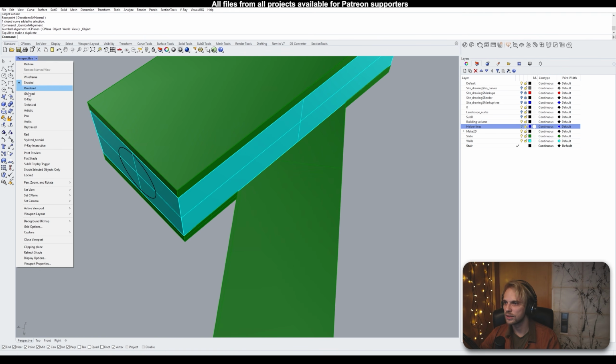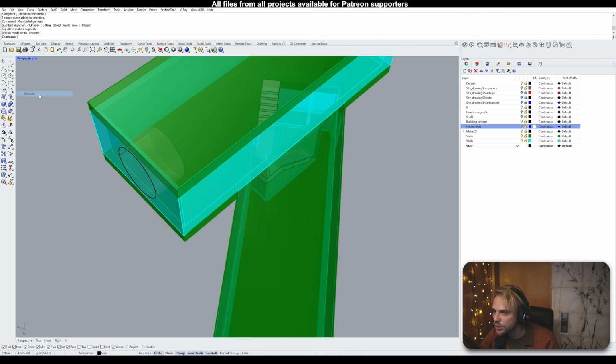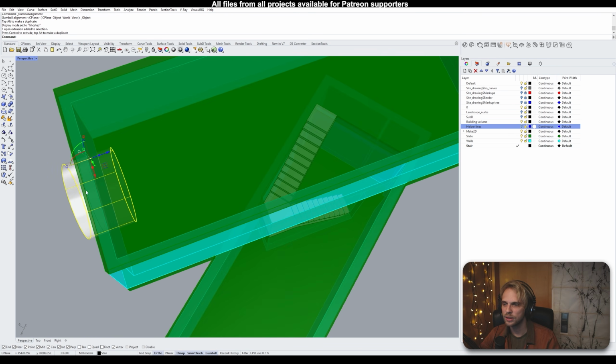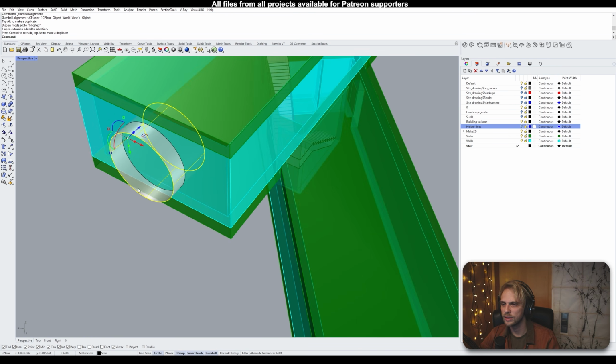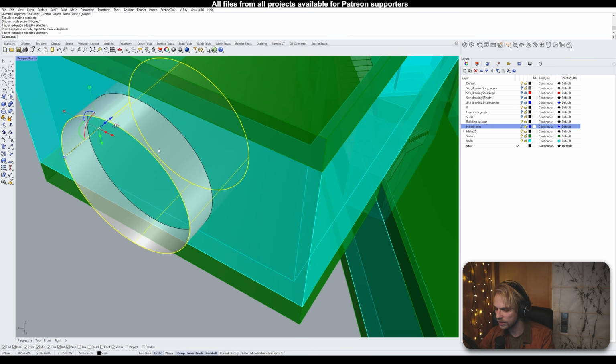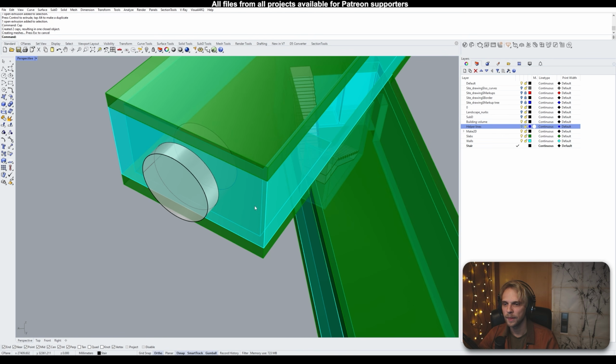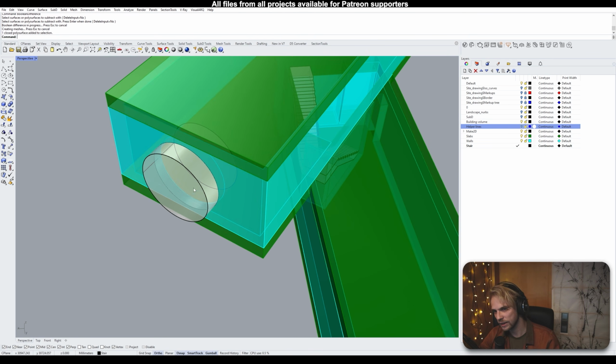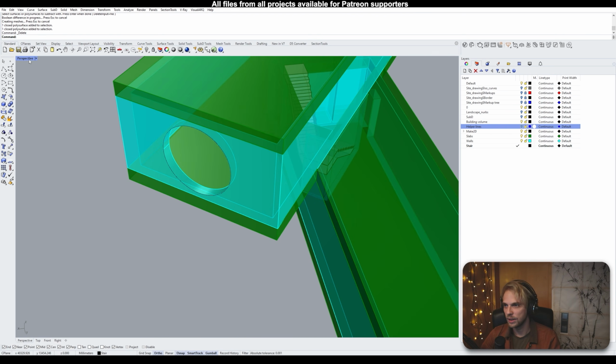into the shape, let's change to ghosted preview. You can see the extrusion there. Let me move it out a bit. You just basically need to make sure that it's intersecting, right? Select the cylinder that you've extruded, cap it, type in cap, and then just use Boolean difference with this cylinder that is capped, and you get a hole.